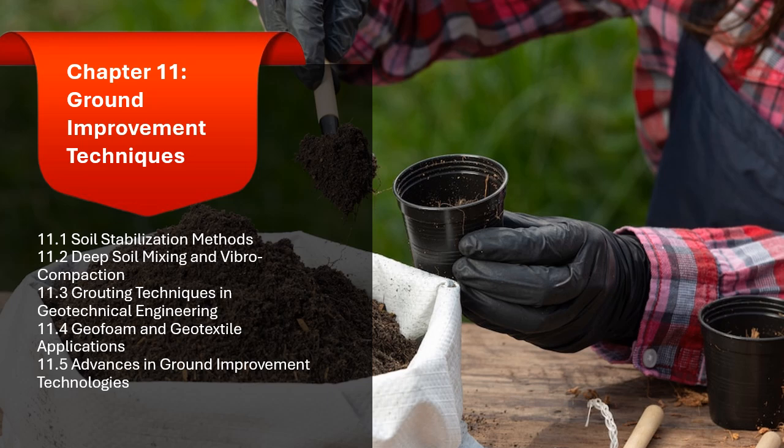1.4.2.2 Applications of geotextiles. 1. Soil reinforcement. Geotextiles are commonly used to reinforce weak or loose soils. When placed between soil layers, geotextiles improve the soil's load-bearing capacity by distributing the applied loads and reducing the potential for settlement.